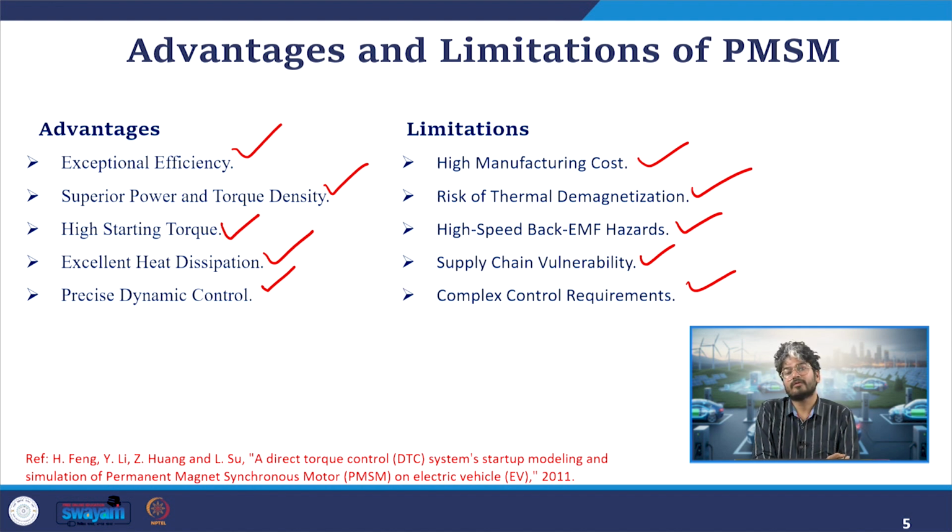What will be the other way of starting the PMSM? We can have a position sensing system, that is an absolute encoder, which will give us the absolute position of the rotor circuit, or the other option is we can have a resolver. A resolver is an advanced version of the encoder, which will directly give us the position of the rotor. Why is this important?